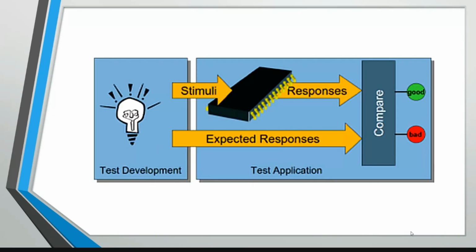Now all of these need to be tested first, so whether it is really at fault, which one is at fault, we should be able to diagnose. That diagnosis feature: how do you test? How do you know that this particular IC, out of all these multiple ICs on the board, is failing? That also can be detected using board test, but not just board test.